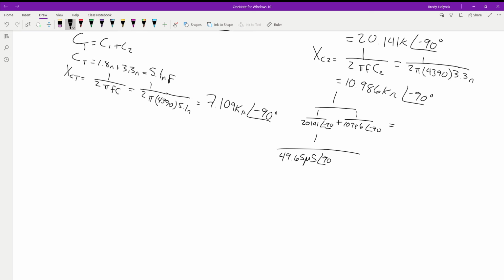We are finding the total reactance. Sorry. Yep, we're just double checking this value. So I'm just showing you the process of how we do this. So we take the inverse of this guy, which is going to give us the conductance value essentially. We're going to add that to this value. So we have the 10,986. We inverse that one, and we get 91.025 micro.